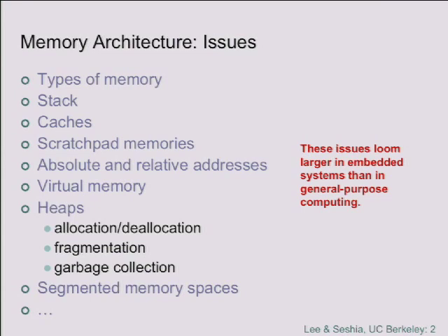Sorry? RAM is volatile. So if you... well, actually, RAM technically means random access memory, and flash memories are RAM. You can do random access on flash memories, and they're non-volatile. DRAMs are volatile. Dynamic RAMs.